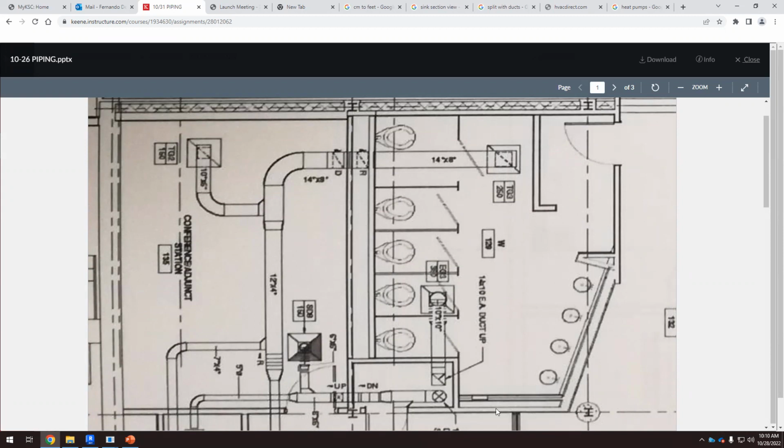And this cavity is bigger than the other cavity. This is for the drainage. Okay, so for the piping, it wouldn't be necessary, but we have to get rid of all the waste here. And we need a space between the wall and the following wall. Okay, because then it has to go all the way down because the drainage system works with gravity. And gravity means that it has to go down.